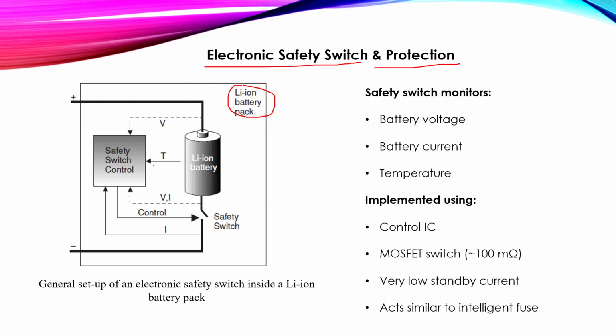It continuously monitors voltage, current, and temperature. If any parameter exceeds limits, it disconnects the battery. It works similar to an intelligent fuse, but with controlled delay. Since it is always connected inside the battery, it must consume very low standby current.